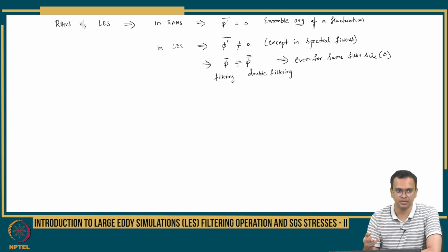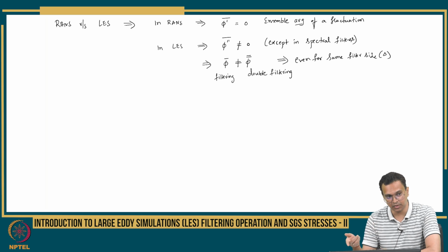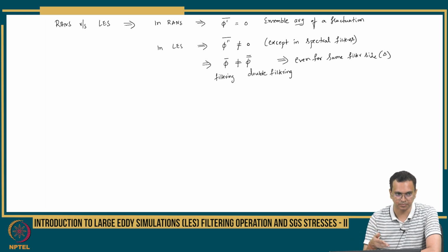But when you run LES, by default you are running for random velocities and random pressure quantities. If you want the mean, you have to do post processing, an averaging operation, a time average or whatever you want, to get a mean velocity and a mean pressure and separate the fluctuations. From the separated fluctuations you can get Reynolds stresses, right? That's the whole point. So the overbar has a different meaning here. When we take this concept to governing equations, you will understand what we mean by that.